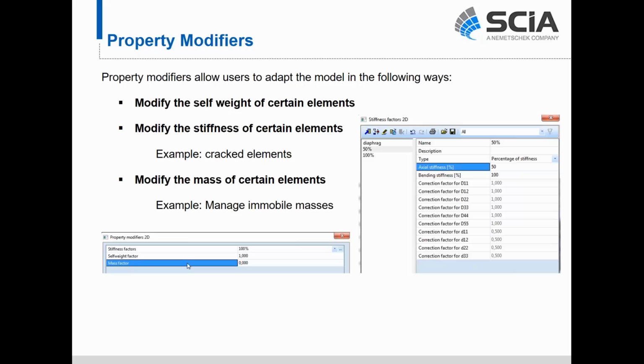Maybe in this case it's the mass of the parking garage that's below grade, not having to be taken into account for the remainder of the analysis of the pedestal building, or the building that's above the parking garage, right? So this really allows us, in that case, not only to get more accurate results, but now maybe you don't have to build 2 separate models, right? So you don't have to create more work for yourself because you're trying to get the seismic analysis to work the way you want.